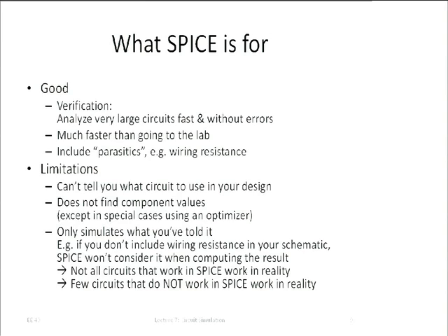So very often what we do is, if we suspect, for example, there is a wire and the voltage drop across that wire could be significant, when we do the simulation, we actually stick a resistor in to model that voltage drop. And then if we get a result that is different from what we expect, then we go and figure out whether it's that wire resistance. Okay, so things like that. We will look shortly at other components where we will make idealizing assumptions when we do the analysis. Very important, because then we get a result quickly and we keep overview. But later we're going to use circuit simulation to verify that the actual component that is not quite ideal will also perform as we intend.